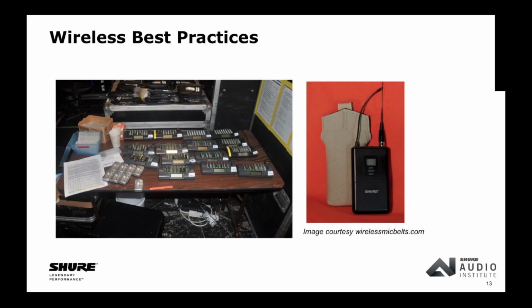Like I said, I put the pack upside down to keep sweat out of the connector, because I've had an actor who was perfectly fine right before the curtain came up. The curtain came up and they had sweat in the connector, and all it was was crackle. Sweat in the connector, straight crackle. Yep. So we do that.